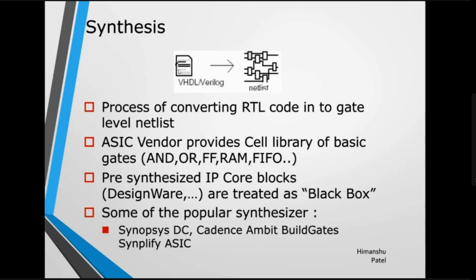If it is a two input, one output AND gate, then you will have that module definition. Library means module definition. Remember this: when you say library, there's a module definition of that particular cell, whether it is a combinational logic gate or a sequential gate. When you say library, that means the behavior as well as the functional logic of that particular cell.